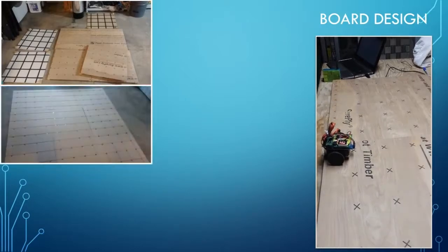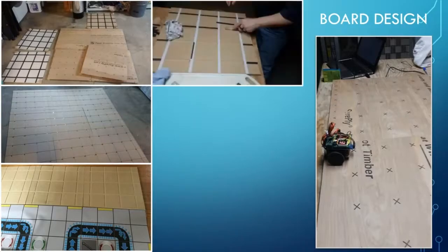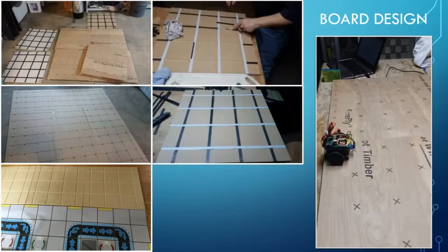And so once we had our prototype assembled, we decided to make a much sturdier board out of MDF. And we put those little neodymium magnets at the center of every square. You can see how that lines up with our printed mat. We want that neodymium magnet in the center of every square to provide a big old spike of magnetic field so the robot could count that as spaces. So you can see, if I moved X number of spaces, it counts the spikes in the magnetic field as it moves. And so then we would fill in those grooves we'd cut with magnetic tape. And you can see what a fully assembled board would look like.